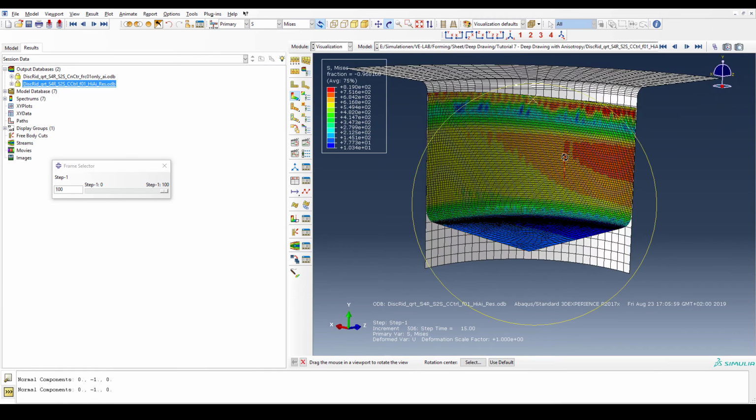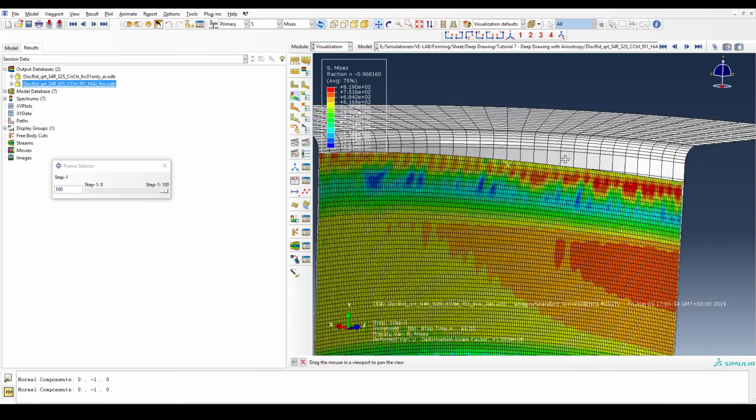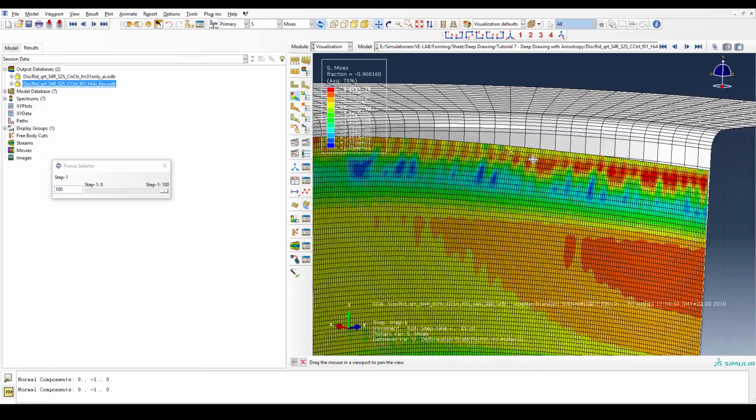But here you can nicely see, if you artificially scale up your anisotropic values, then you have this typical earring, what you expect, right? You have a higher edge and a lower edge. And given the Hill condition, it will always give you two ups, that would be on this side and over here, and two lows, which would be over here, 180 degrees across that low. But again, you can see maybe even more pronouncedly this waviness pattern.